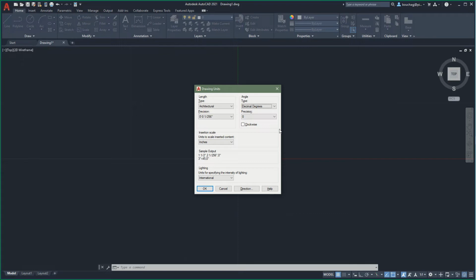Conversely, and similar to the discussion regarding precision values for length measurements, for example, creating a geometry that has an actual angle of measure of 22.5 degrees, when an angle of degree measurement is applied to this geometry, the displayed measured value will be rounded up to 23 degrees, since the overall unit of measure value for angles is lacking a less than whole degree decimal precision setting.